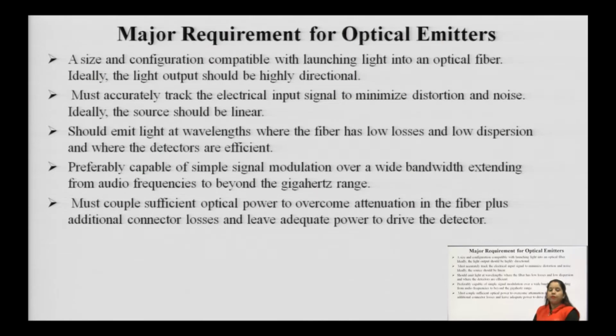Now, before moving towards the LED, first we will study what should be the major requirements for any device, equipment or component to be an optical emitter. The first one is that the size and configuration should be compatible with launching light into an optical fiber, that is, the light output should be highly directional.